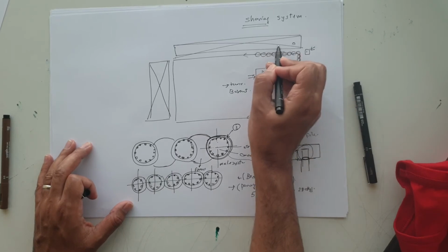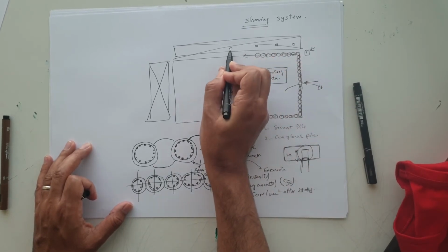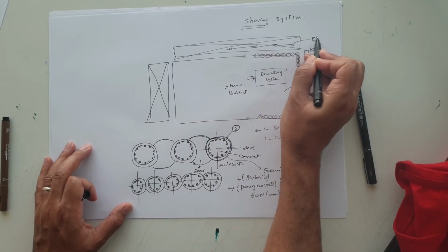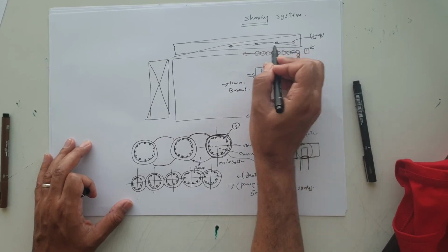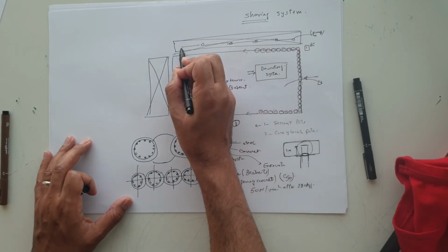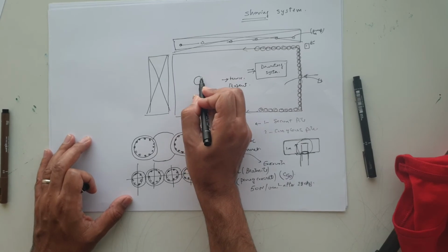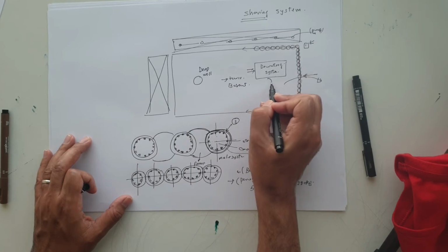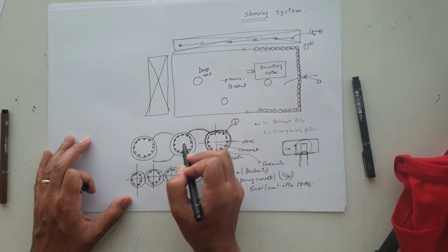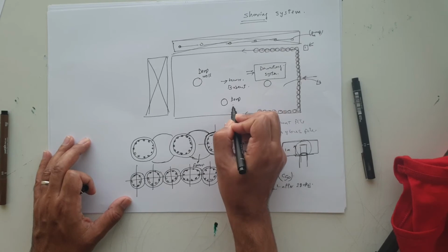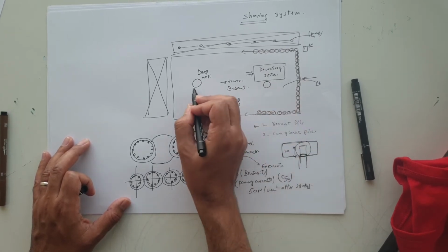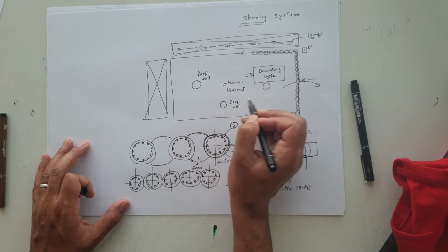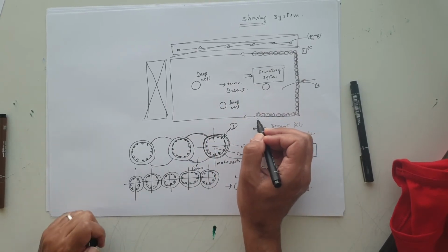We can use the pipe system from outside, and this pipe is affixed to the pump to shift the water around the project. Or we can use deep well, 2 point, 3 point, depending on the area of the project. Also the same issue, it is fixed with the pump, and we use the pump continuously working inside the excavation area.